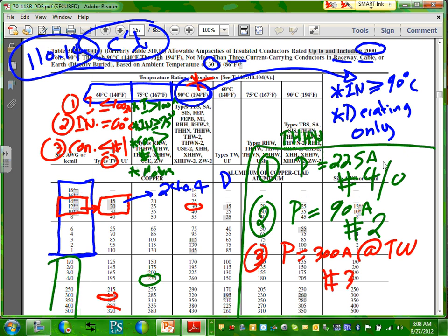Am I doing this right? 300, see, the 300 gives me this one here, which is, no, 300 wouldn't give you that. No, thank you, I just can't read it from here. So for 300, you have to almost go to the 500. Number 500 kcmil. That would be a bad idea, right? That's why we use the THHN, right? See why we use the THHN? 500 amps or 500 kcmil? 500 kcmil. Amps, Chad. Where did they get the amps? Thank you.